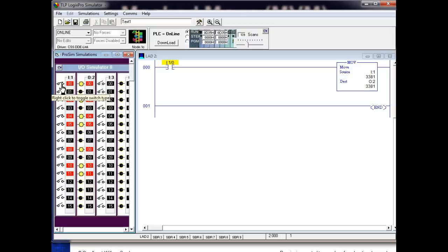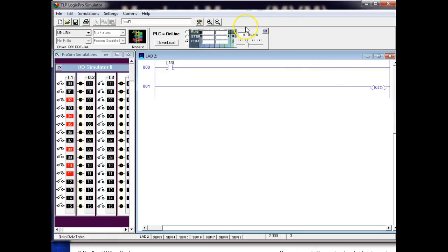So how do I strip those off? We could do an AND mask. I could move it and then AND it. The most predominant mask that we use is the AND mask, a lot more than we do OR mask. So I could do it with 2 instructions or I could do it with 1 instruction. I'm going to take this guy here offline, delete this guy, and instead of using a move, I'm going to use a move with mask.